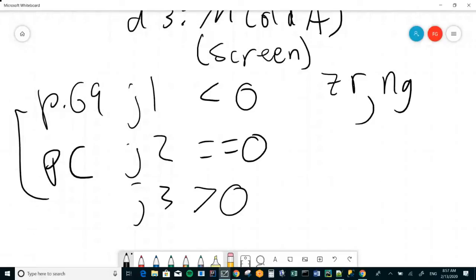And the same thing for this, and then greater than is a little more complicated. But you can certainly derive it knowing the 0 and the negative flags. Basically, if it's not a 0 and it's not a negative, it's a positive. Sadly, our ALU doesn't have a PS output, but it's really 6 of one, half a dozen of the other, right? You could have put that circuitry into the ALU and had an extra output and had an abstraction here, or you can just do it right here.